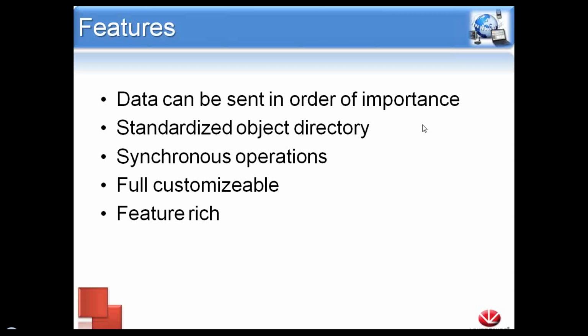It's going to have all the communication parameters. Anything that you need to read or write to the device is going to be located in the object directory. It is standardized. There is also a group of common commands that we can send that are universal across all CANOpen devices. So if you know your way around one CANOpen device, you'll be able to operate around another.